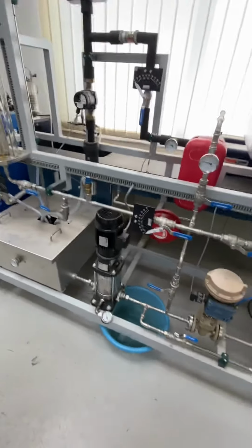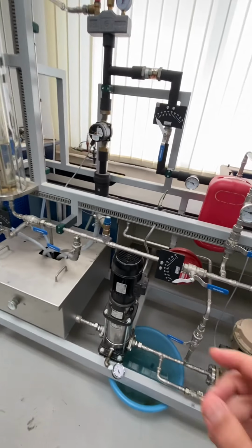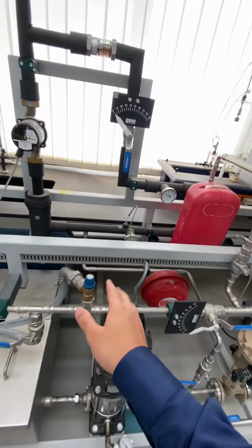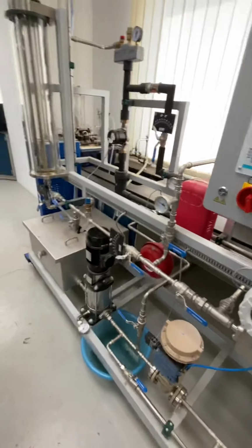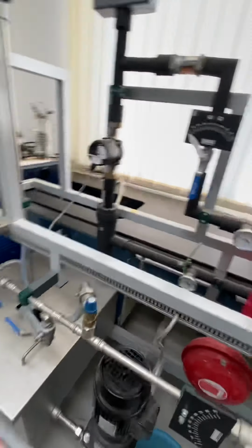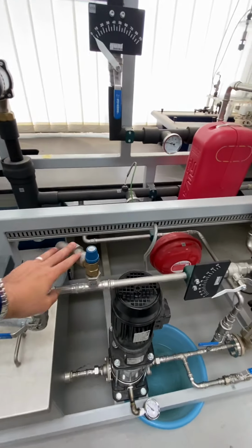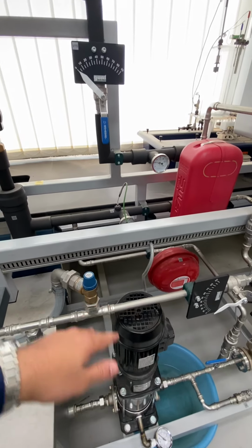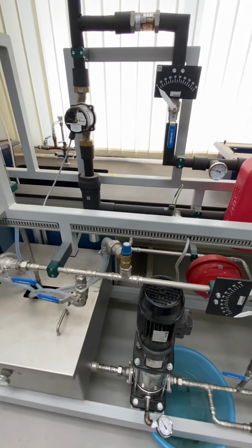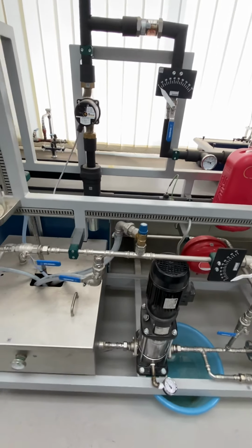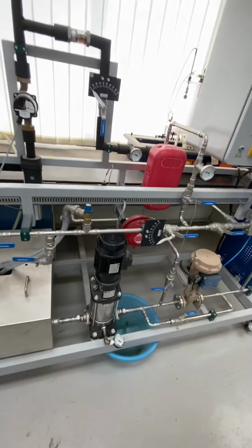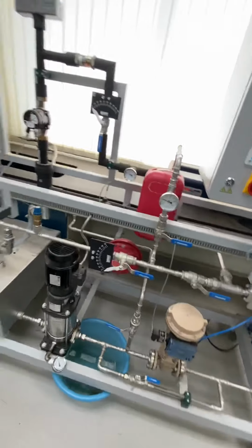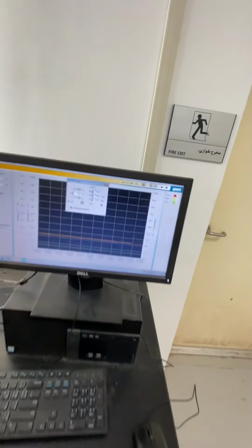Okay. Now, one of the problems that might happen with the safety valves, guys, is that they open and then they get stuck open. They don't get closed again. Okay. And it is actually very difficult to detect because, as you can see in here, there are no instruments upstream or downstream of the safety relief valve. I have no pressure gauges or flow sensors after the safety relief valves. So if it gets stuck open, guys, you might see that the process value is at the set point, okay?